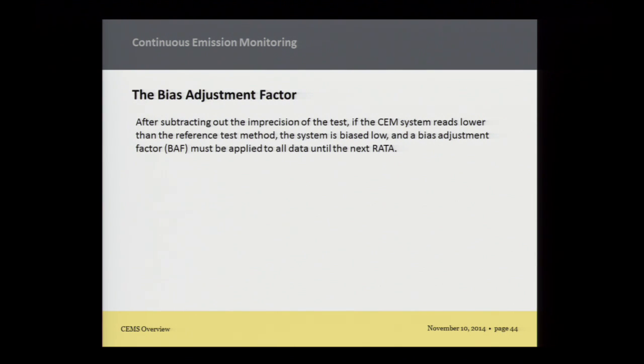You may very well be applicable to both Part 75 and Part 60 on the same unit at the same time. Just because you fall under Part 75 doesn't get you out of doing Part 60. And yes, most Part 75 systems do have multiple calculations for the same parameter, some of which are biased, some are not. Some follow different validation rules for Part 75 versus Part 60. So it can kind of get confusing because you get different numbers for the same thing. Yeah, you're correct.